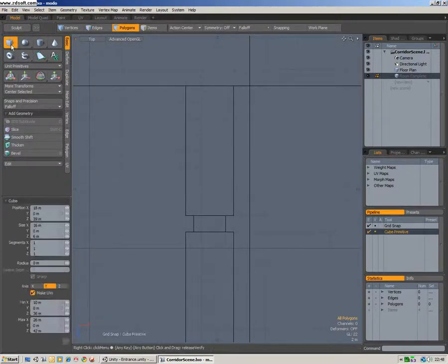We're going to select the left click on there. Make sure the grid snapping is on. Left click. Drag it out. Let go. And then in Modo you'll see these tool handles. These are just so you can rescale or remove what you already made. And the arrows move the whole thing.